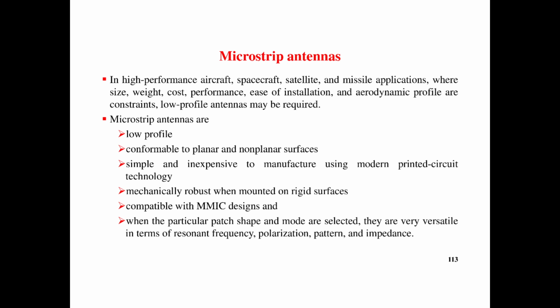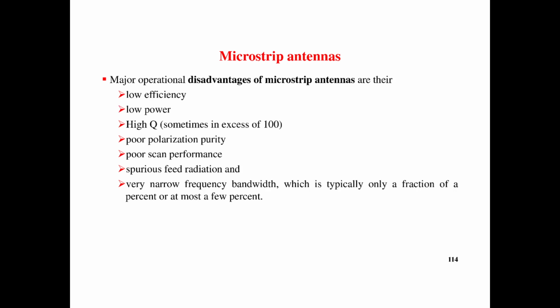Microstrip antennas are low profile, conformable to planar and non-planar surfaces, simple and inexpensive, mechanically robust when mounted on rigid surfaces, compatible with MMIC design, and when the particular patch shape and mode are selected, they are versatile in terms of resonance frequency, polarization, pattern and impedance.